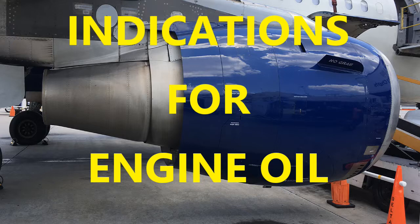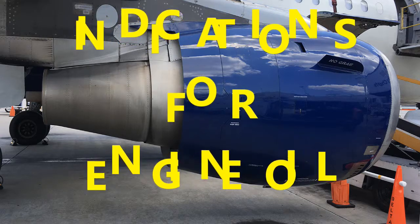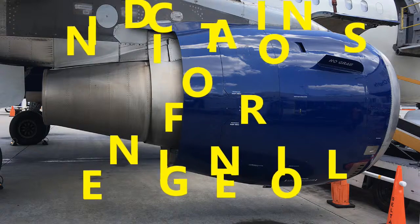So back on quantity, I mentioned the level. Do follow, of course, what's in the manual as far as the minimum quantity of oil that's necessary, and then also whatever is necessary for that flight, for the aircraft to fly. Obviously, that's not going to be exact, but it's going to be that minimum quantity plus extra. Okay, so be aware of that.